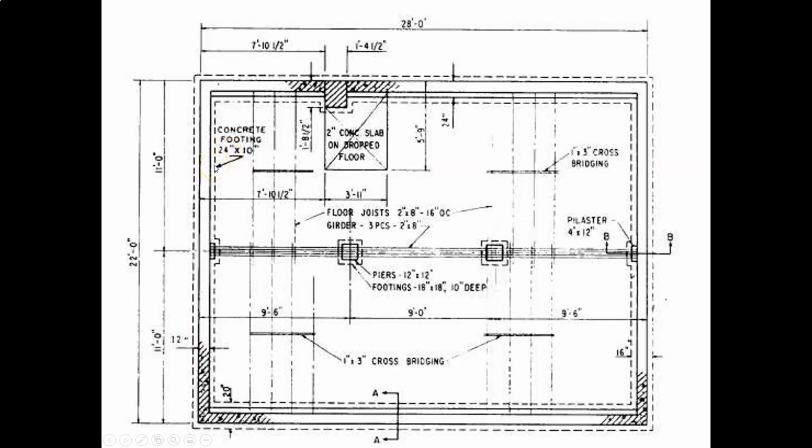The difference between that is 1 foot, right? This is a foot, that's 2 feet. So that tells us that this footing is a foot thicker than the wall. So this is an additional 6 inches, and this side is an additional 6 inches, right? So it's going to be 6 inches of footing, 12 inches of wall, 6 inches of footing. That's how we get that 24. So if we know that this is 6 inches, we're going to have to come over here to the 28 feet, and take that dimension and pull it over 6 inches. And this will become 28.6, 28 feet, 6 inches.